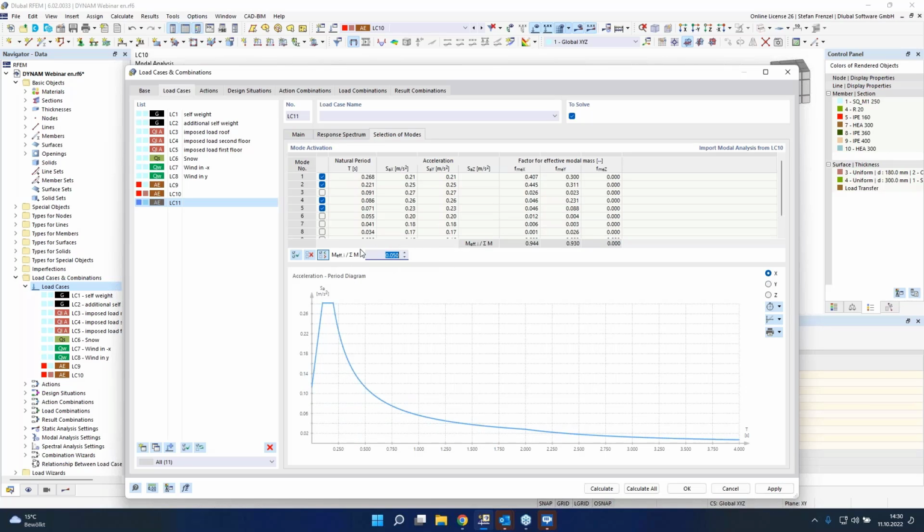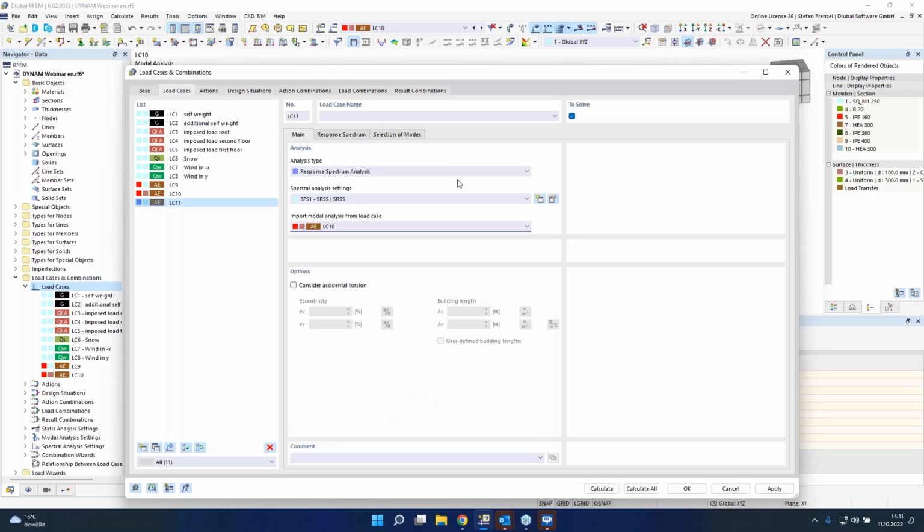So we want to use the 5% value. The program is already also over 90% in some of it, but we just need 4 eigenvalues for that. And that's the important thing. So that's also a performance point, just to use the eigenvalues which you need and not all eigenvalues. Then we can go back to main.